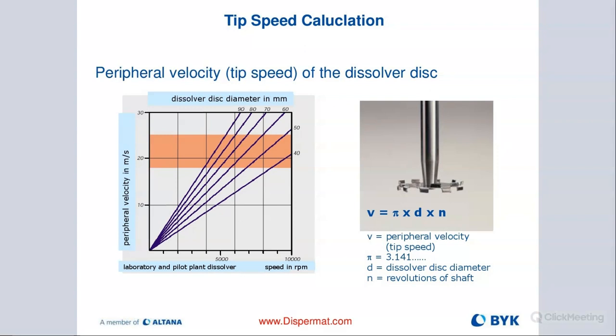And one other thing that's important when we are pre-dispersing is to remember that we are putting energy into our slurry. Usually the pre-dispersing time can be up to about 1 hour for particular materials. Usually it's faster, but since we're putting in energy, it's important to also cool our slurry.